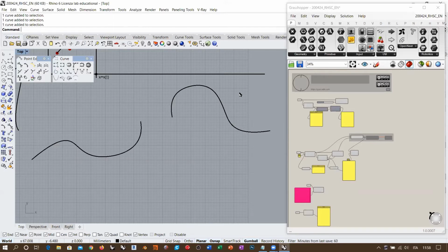G3 and G4 also have a funny name in terms of derivatives, because G1 is basically defining the direction, which is tangency, then there is G2, which is curvature, and then there are G3, G4, G5, and you can go up to G whatever you want if you think about it, okay? Because as long as your equation allows first, second, third, fourth, fifth degree derivatives, then you can go on and on and on and calculate this new function, okay?